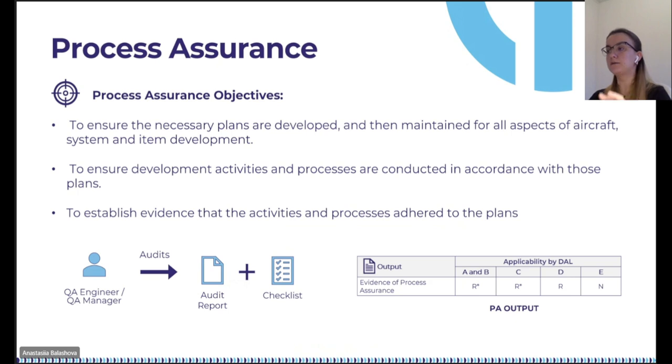Please do not confuse the role of QA in the aviation sector and in the IT sector. In IT, QA is responsible for system verification, which is testing. In our field, QA is about processes. The QA's job is to make sure that we follow the correct process in development, and he or she is usually not involved in technical issues. This is a very critical role, and please do not underestimate it. In my opinion, only the best of the best become QA engineers.